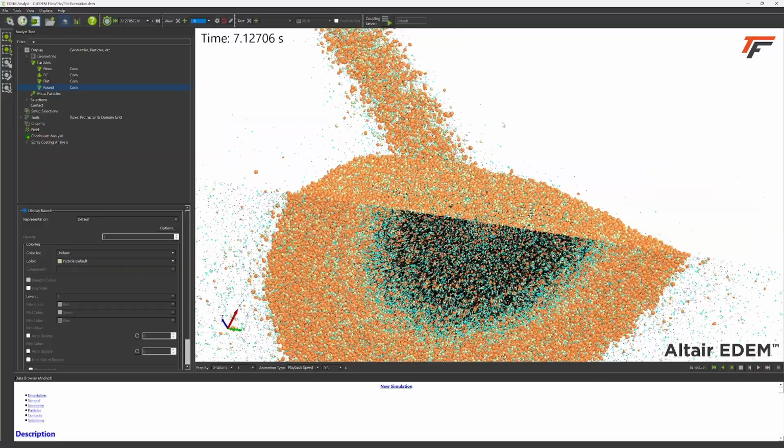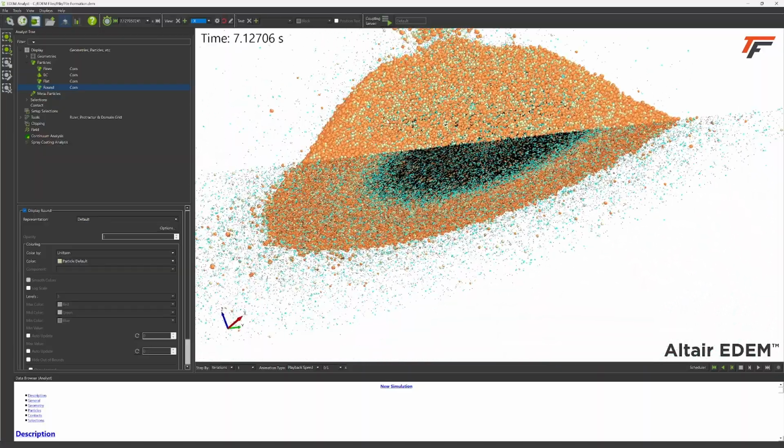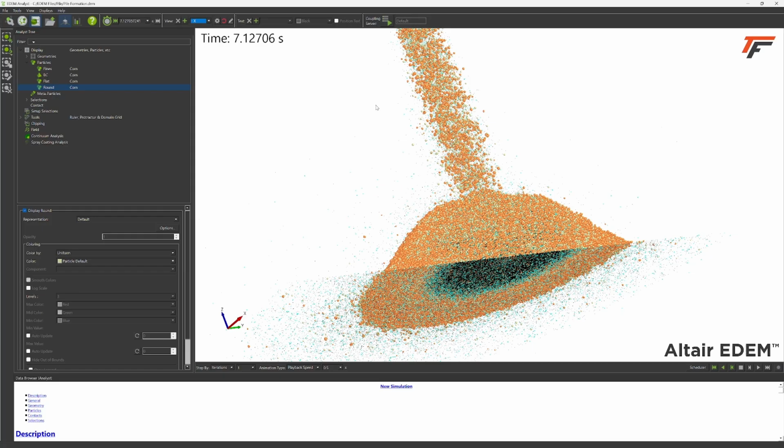In some of our research and some university research, they call this the air bypass effect. Meaning, if air can't get through this area, it's going to trap excess heat from drying. And that excess heat is going to trap excess moisture from drying. It's not going to cool as fast. And these areas, as they lock on and hold that heat maybe for several days or weeks, are going to become a breeding ground for microbial activity.